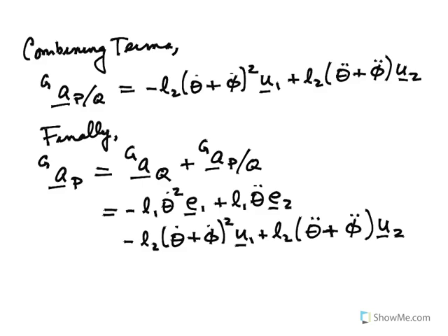But without getting into all of those details, right now the main thing is that you want to do the calculations using a basis fixed in whichever frame is most convenient for that piece of the calculation. In this particular case, it was most convenient to compute the velocity and acceleration of point Q as viewed by an observer fixed to the ground using coordinates that are fixed in the first arm. And it was more convenient to compute the velocity and acceleration of P relative to Q as viewed by an observer fixed to the ground in coordinates that were fixed in the second arm, and then combine the two results. So that's exactly what we have here.